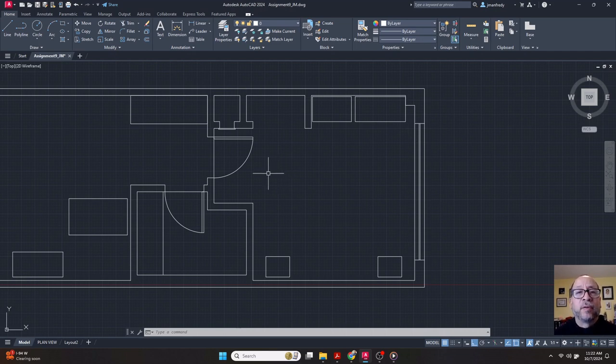The benefit of having a folder of existing drawings that you produced in the past is to be able to access those drawings and reuse the information within those files. In this case, reuse blocks. If there's a drawing that you produced in the past and you created blocks within it, you can reach into that drawing and pull out the blocks for use in a current project.